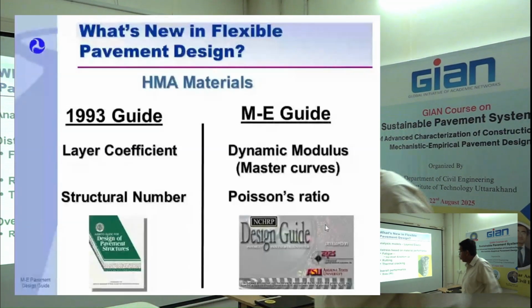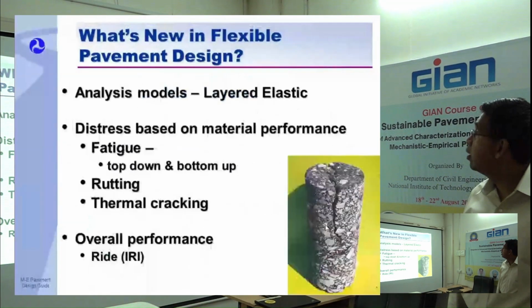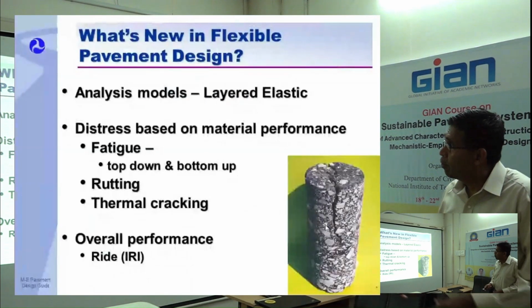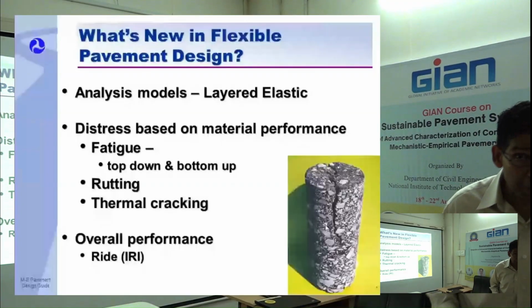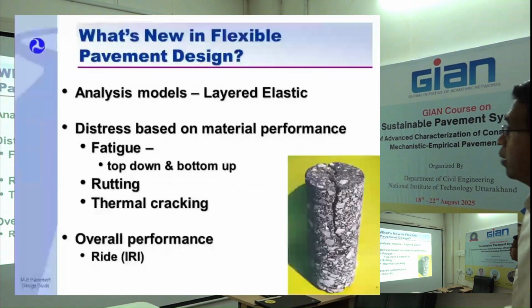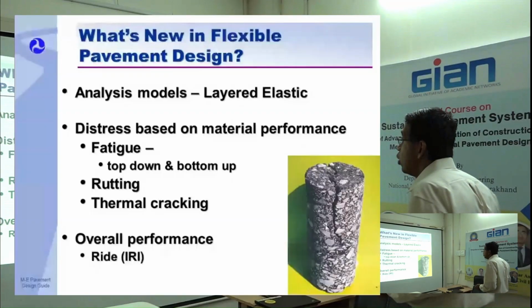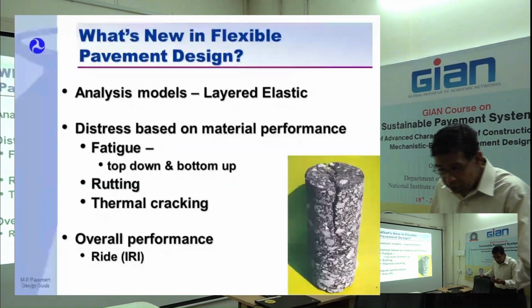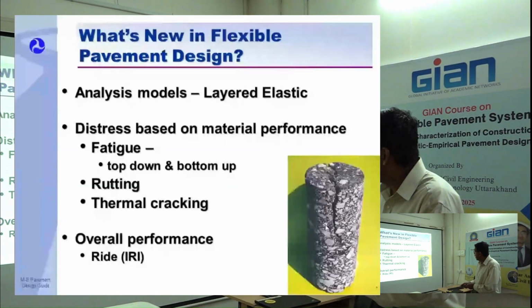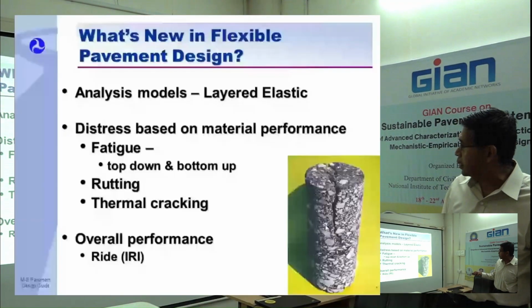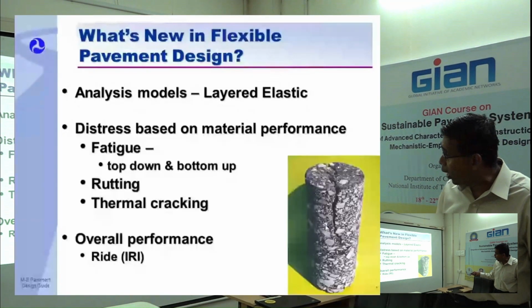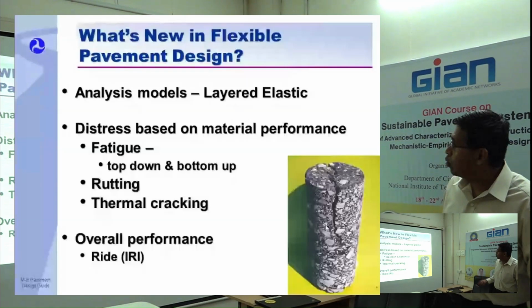Analysis model. What's new in flexible pavement design? You have layered elastic analysis, right? You have to do layered analysis because of speed, right? Otherwise, this becomes very slow. You are looking at stress-based methodologies, top-down and bottom-up cracking. Top-down, remember I told you, causes fatigue cracking, and here is the very classic example of almost like a pristine case where you know where the damage happened, right? And you can analyze that as well.